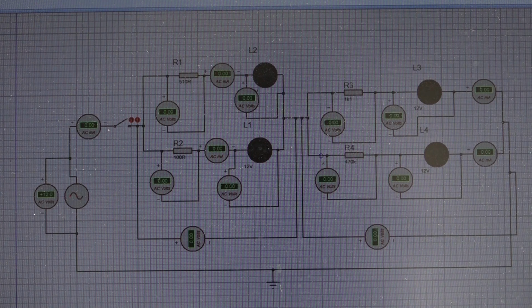Oh, so what is happening there? Can you show me? You see 0, 0, 0. Every point 0, 0, 0. Then you get confused that, I did everything, but the circuit is not working. Look on the blackboard. All the 15 measuring instruments read 0. It's just only one AC voltmeter measuring the voltage across the alternator that reads 12 volt. Then you panic. But the trick there is very simple. We didn't turn on the switch.